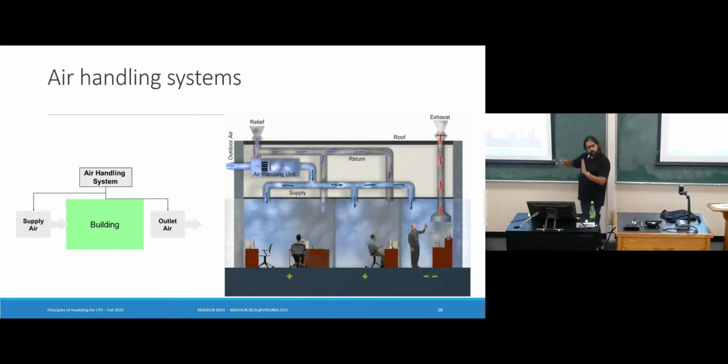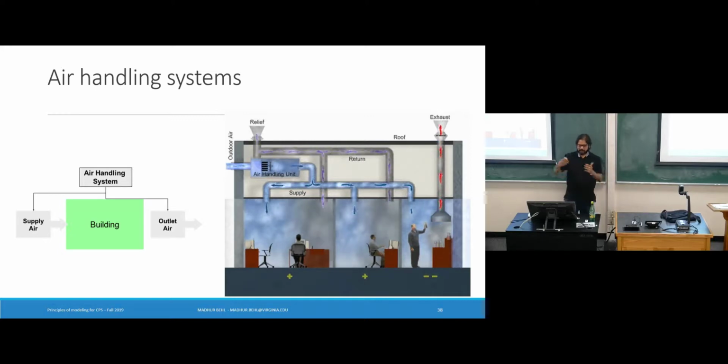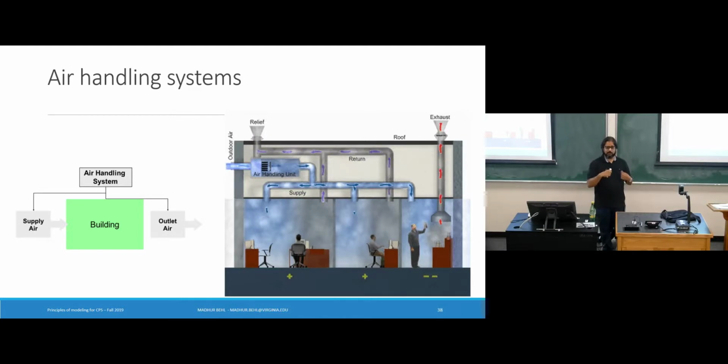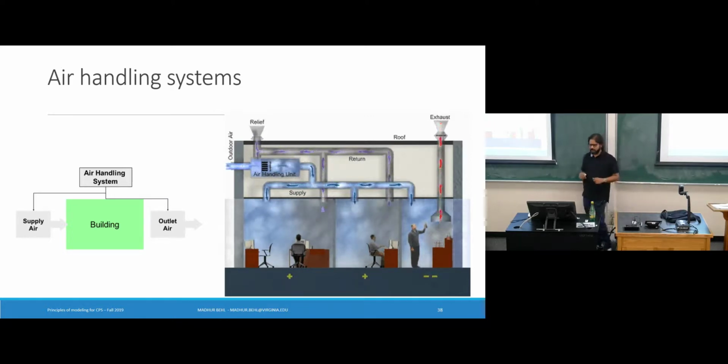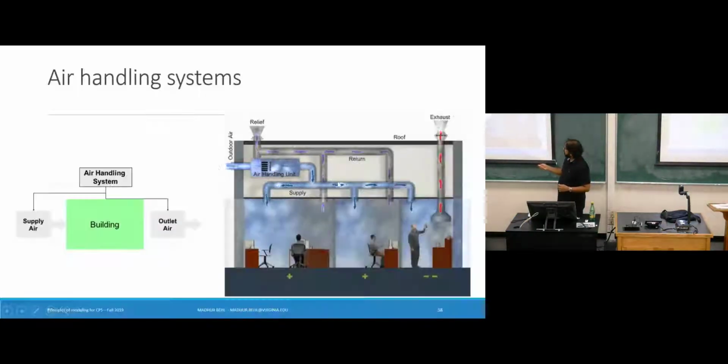And so we are pushing cool air into the zones. In the zones, we have our water bottles, which are emitting heat, so the cool air becomes hot. And there's another system which is now pulling this hot air outside, away from the zone itself, so that more air can enter and this heat exchange inside the zone can take place. This is the basic principle of a forced air HVAC system. So this air which is getting sent out, let me quickly change my control. This is not literally smoke.